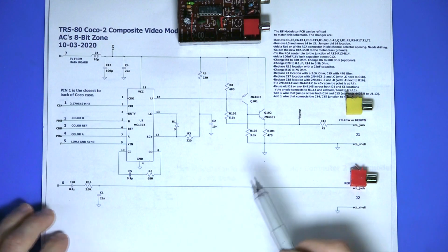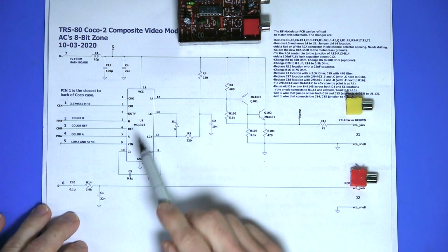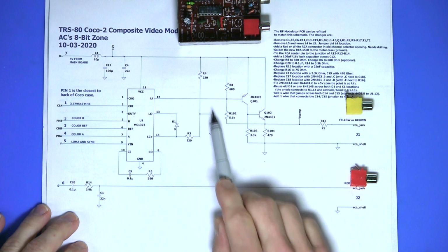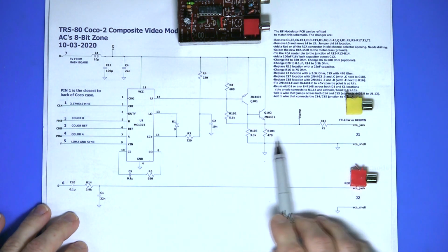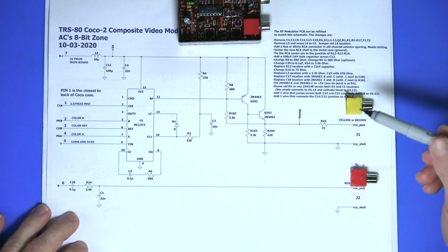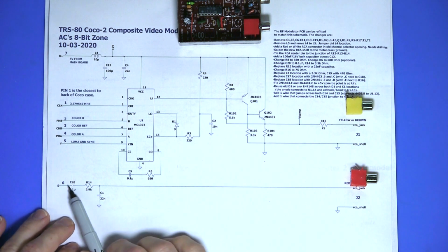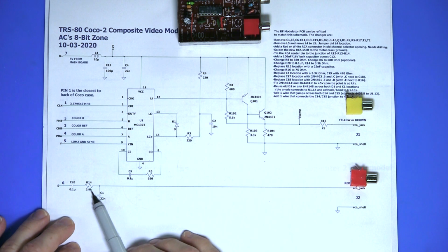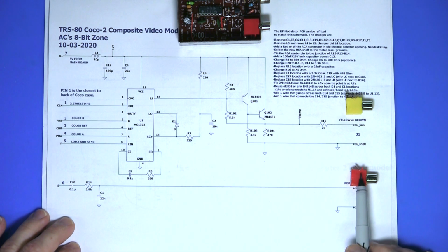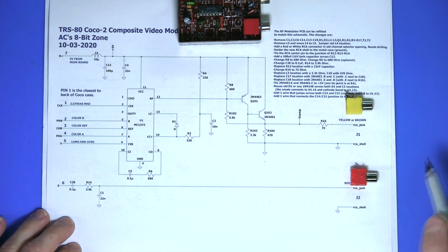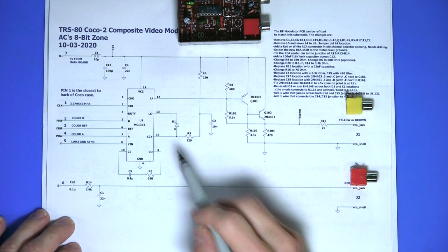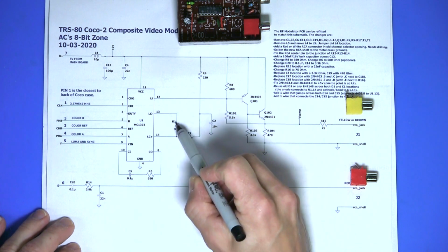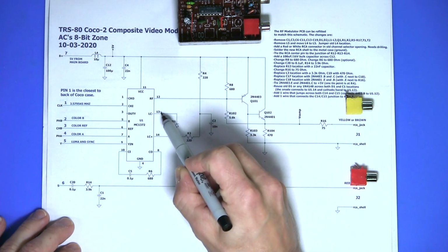So just briefly, here is the circuit. So this is the pin 12. This is the 6847 reference circuit that we already talked about. This is the audio output through a 0.1 microfarad cap and a 3.9K resistor to this red RCA jack. The tank circuit has been removed and replaced with a forward bias diode from pin 14 to 13.